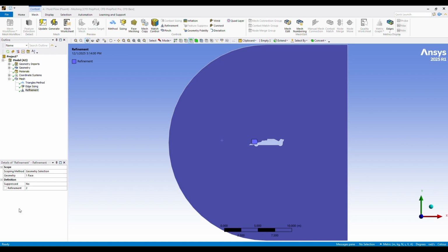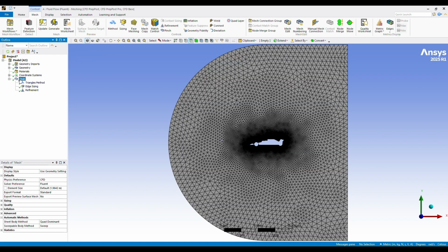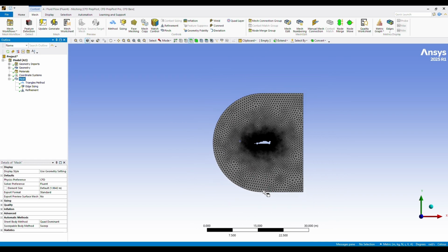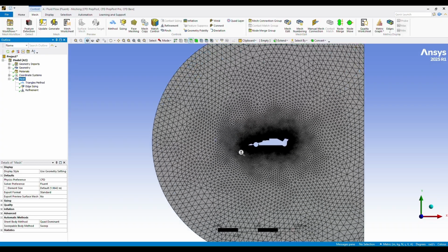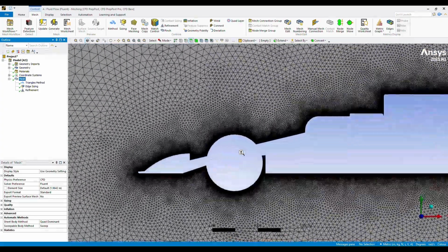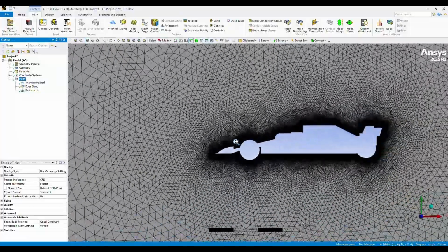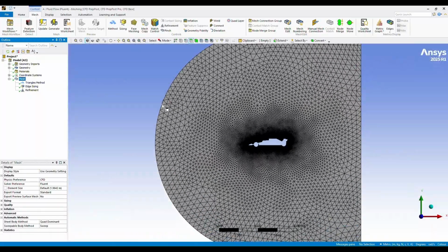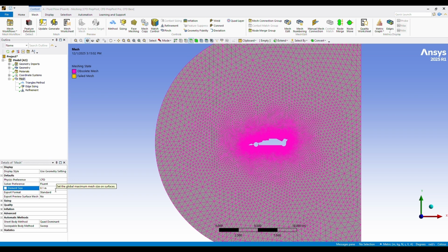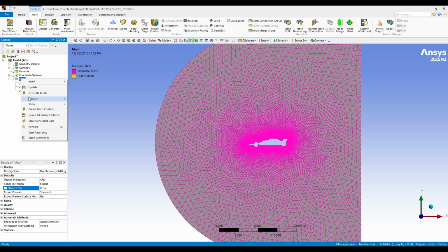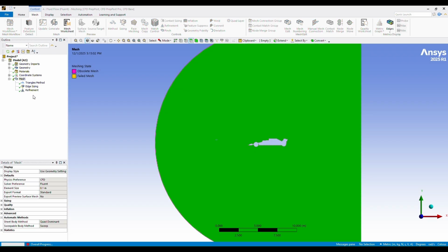okay, now click on mesh and see how the mesh looks. Click. Okay, this is how it looks. Since we have a big element size, it's not looking that good. So I'm changing the mesh element since the inner surface or the edge surface looks good now. Just to check, since the element size is 0.1, that's the element size that I'm using on this one just to make it fine. And now generate mesh.